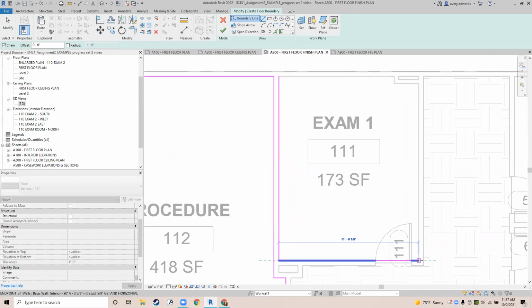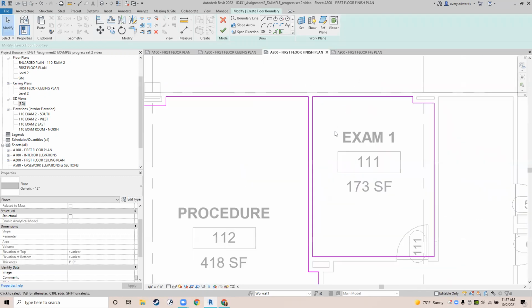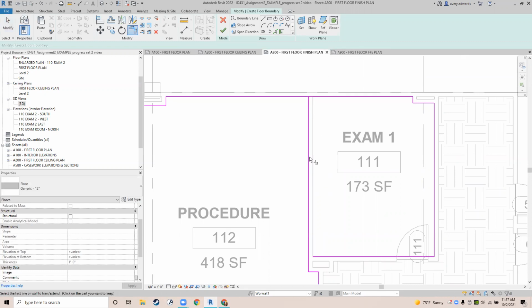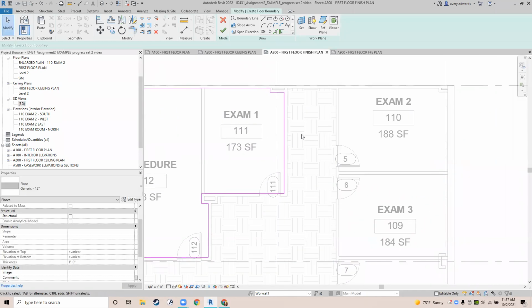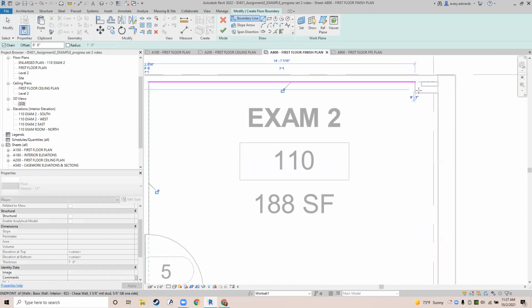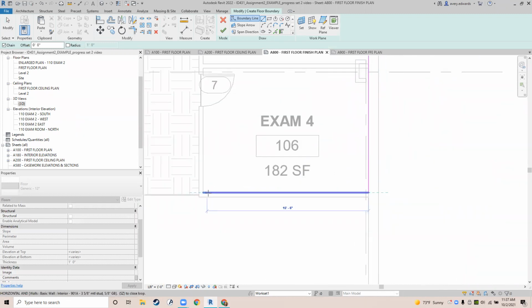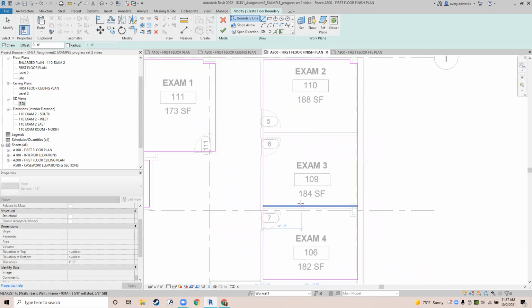Some of you asked in class if it was okay if the floor boundary went through a wall. That's fine. For example, I just traced these two rooms separately, but I could instead do this. I could have it look like that where it's all one. That's fine. It's fine if it goes underneath a dividing wall. So I'm going to do that over here because that's easier for me than having to trace those center walls too.